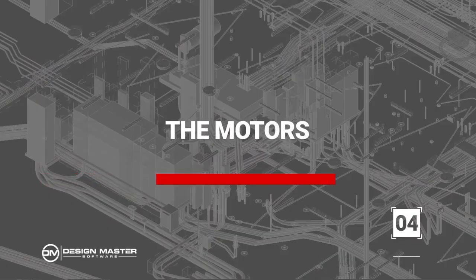Then the 4th piece are the motors. Previously, before BIM, motor contributions were, for the most part, ignored for smaller motors because they don't make a big impact. And in terms of modeling in your calculation package, it's kind of tedious to enter all the little motors in your project that aren't going to make a difference anyway. So generally under, say, 50 horsepower, you're not going to be adding those to your fault calculations.